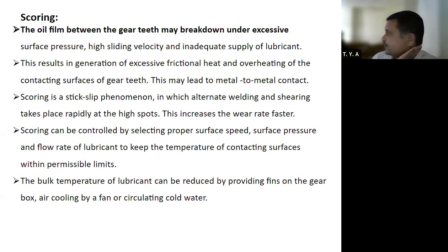Next line: the bulk temperature of lubricant can be reduced by providing fins on the gearbox, air cooling by a fan, or circulating cold water.